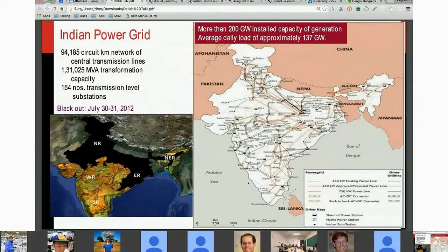So now there are these devices which are called synchrophasors. These are increasingly being adopted everywhere in the world, including in the Indian power grid. What they do is they all synchronize with each other through a satellite and take the snapshot of all these parameters at exactly the same instant of time, right? And that is done several times in a second. And all that data from typically something like 3,000 to 4,000 sensors will now be pumped into the National Load Dispatch Center.